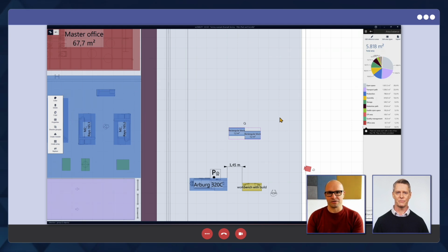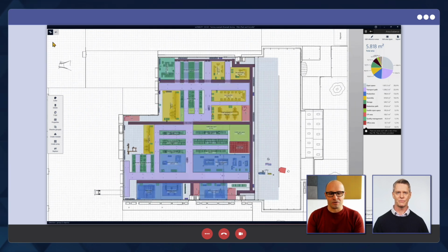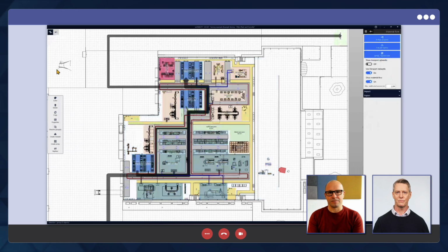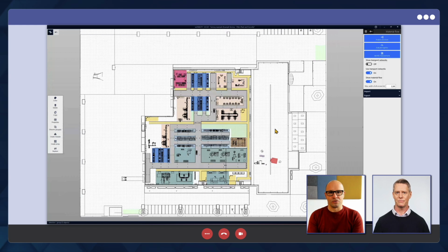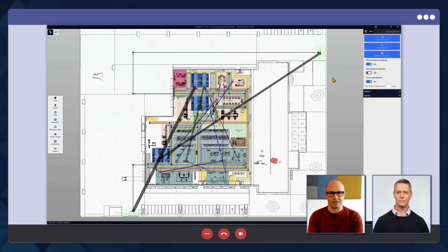We would now come to the point, which was perhaps already seen in the beginning, with regard to the next criterion for evaluating the layout variance, namely the transport effort and the material flow. Here, we already saw in the beginning that a few arrows passed through the layout. On the left side, now I can choose material flow, and I can toggle on and off what to see on the right. For instance, we can now see the material flows as a direct connection from the respective source to the sink. In other words, from where to where does a material flow go?